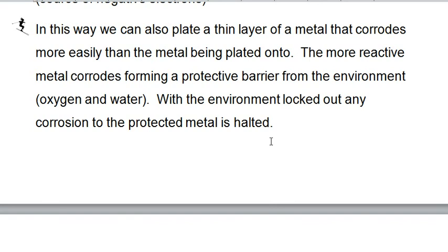When we put the pipe out to make a fence or something like that, the zinc corrodes, but it forms a zinc oxide barrier that prevents any further corrosion. And even if the zinc oxide barrier is wiped away, because the zinc solid is a better reducing agent, it reacts better than iron, it will react instead of iron. It's called sacrificial anode. It acts as the anode, the zinc reacts, and the iron is protected, so your steel pipe doesn't rust. Okay?